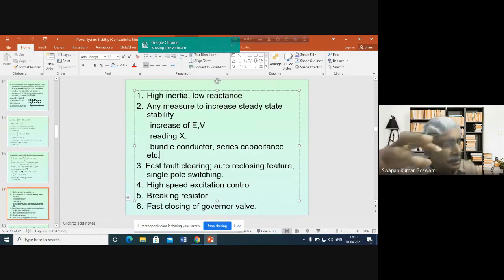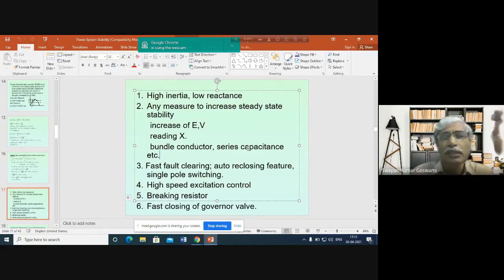There have been situations when, because of the subharmonic current, great damage to the generator has occurred. There is evidence in the past where, because of the installation of a series capacitor, problems occurred in the generator shaft. The generator shaft has broken. This has happened in the past. So this type of problem may occur if series capacitors are used.